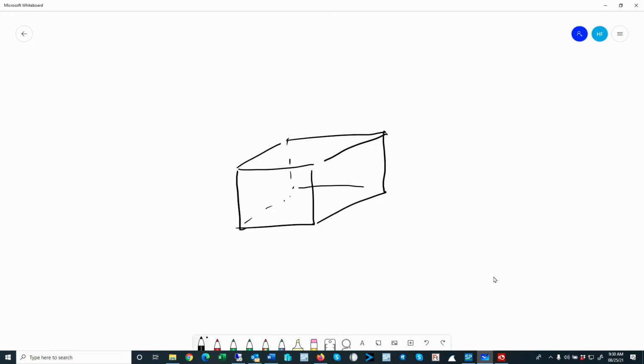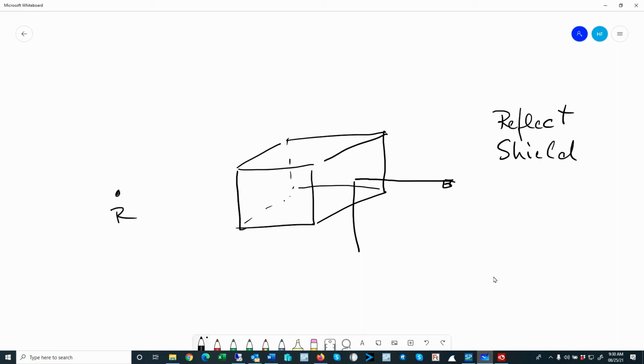An industrial building is basically just like a building, right? The building can reflect. So if you have sources on the outside, they can reflect off the facade. It can also shield. So again, if you have a receiver here, we have a source here, then of course we have multiple paths around it, over it, and on the other side. All right. And then of course for the industrial building, we also have the option that this building can be a noise source.